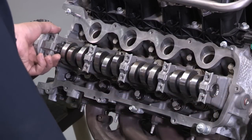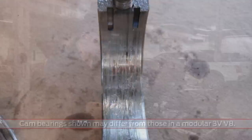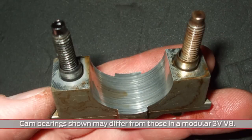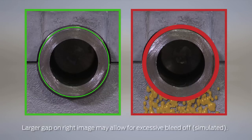Another place to check for excessive oil bleed-off is the cylinder head cam bore. The camshaft and cam caps can also be inspected for excessive damage or metal transfer. Some light scoring is normal, but if the scoring has increased the diameter of the bore to where oil can run out freely, that can cause a problem with the VCT system.